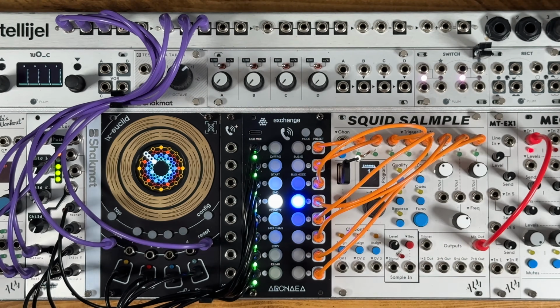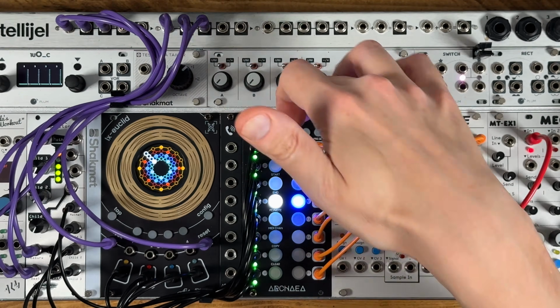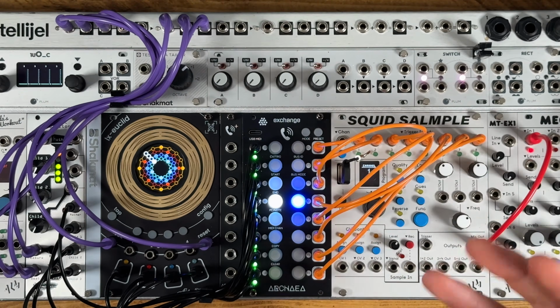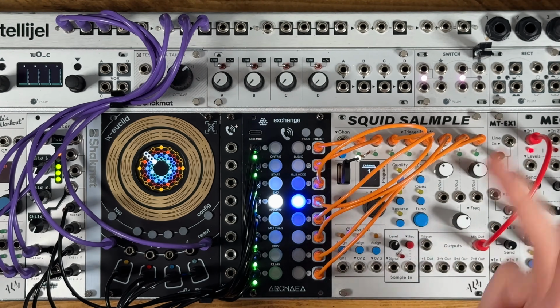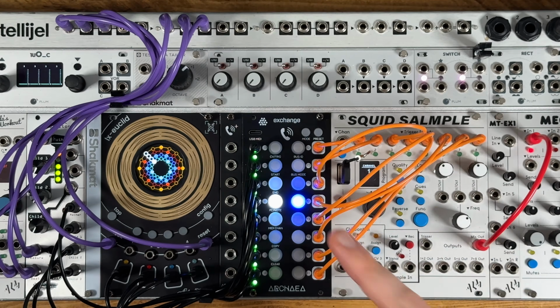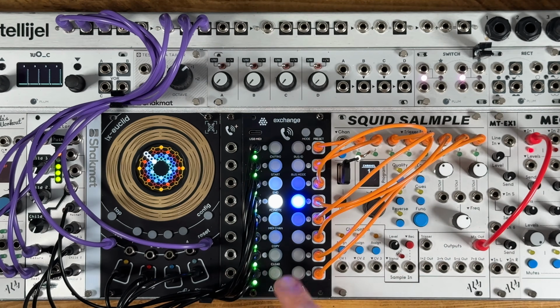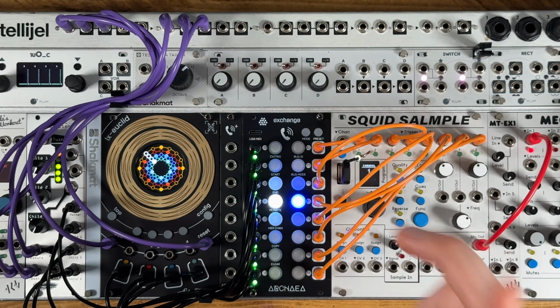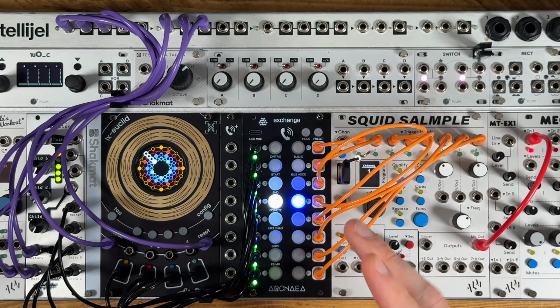There's a USB MIDI input at the top of Exchange. I should say I'm not going to explore the MIDI applications in this video, so I don't really have a MIDI-based setup here, but you can connect this to a MIDI host and then it will accept MIDI CCs to change presets, which is pretty straightforward. The basic idea with preset addressing or preset switching is that you define a start and an end preset from the ones that you've got saved on Exchange. And that defines the number of presets that it's going to skip between. And then there are various modes to change through them.